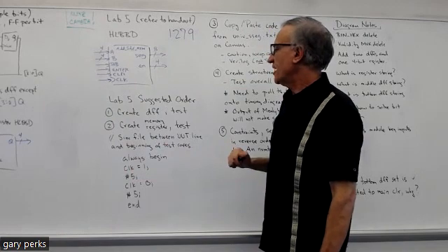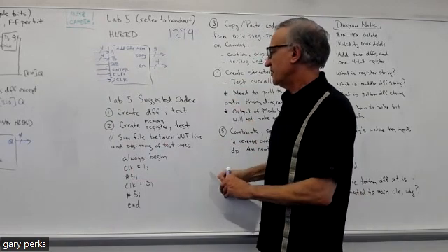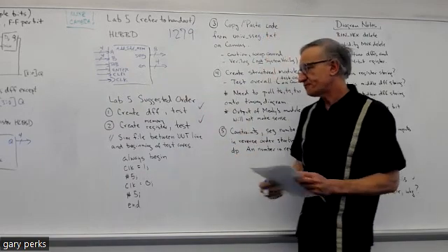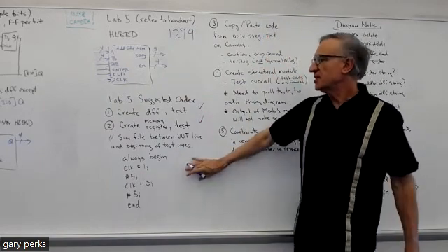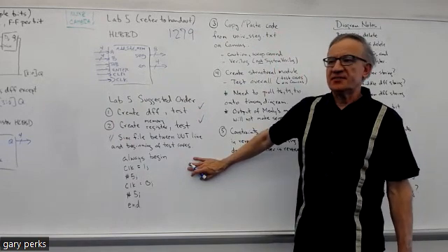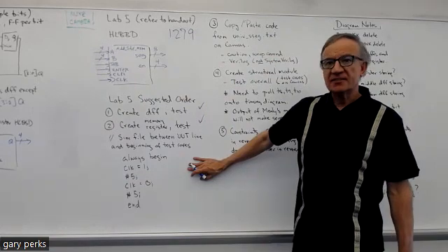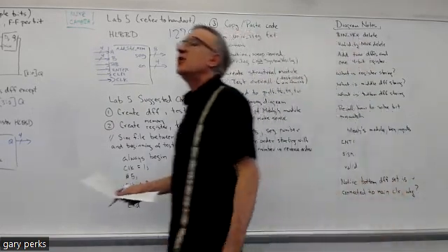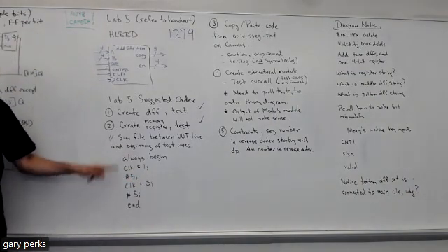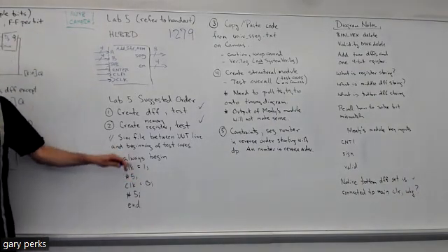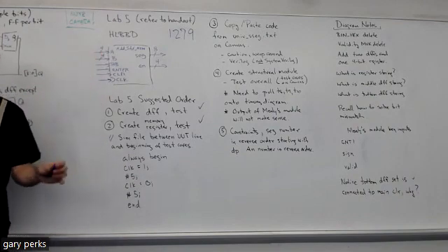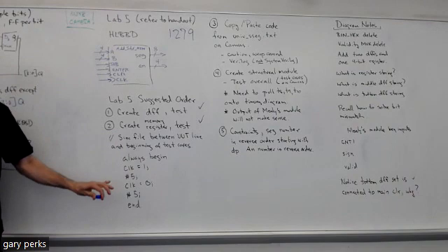All right, so where are we at? Create the D flip-flop, test it, create the memory register, test it. Now, this is something new. When you test a sequential circuit, no matter what it is, it's going to have a clock, and you have to generate that clock signal in the sim file. This is new because everything prior to this was combinational, didn't have a clock, right? So you didn't need this for combinational.